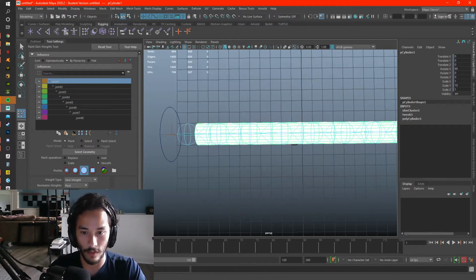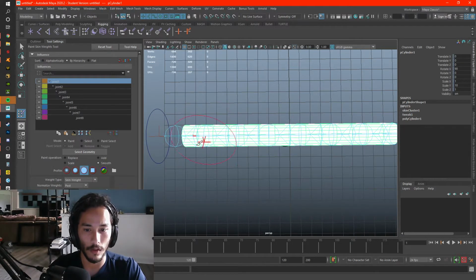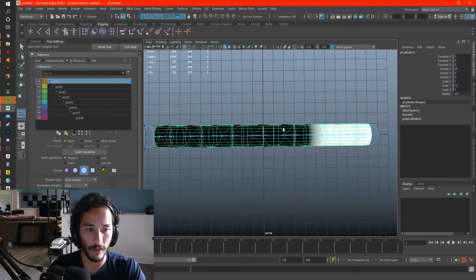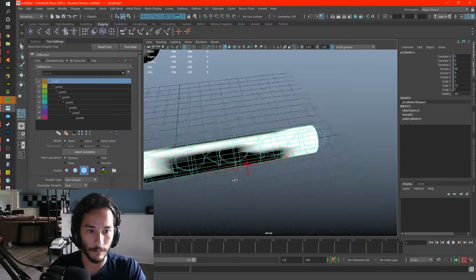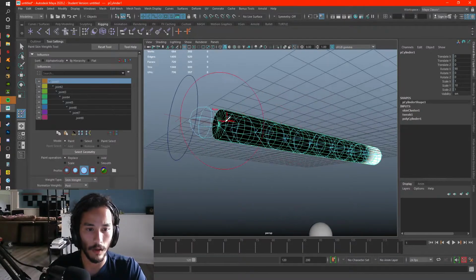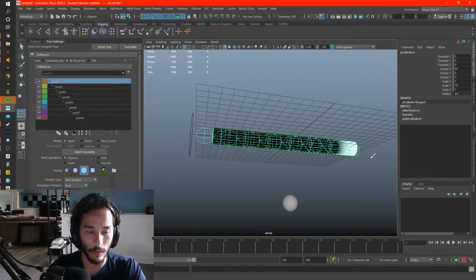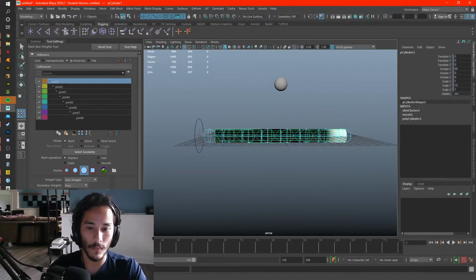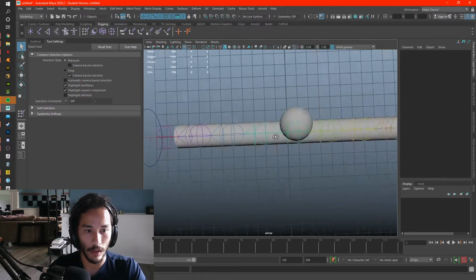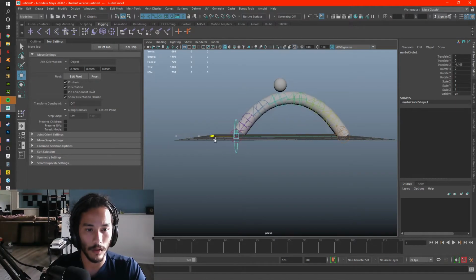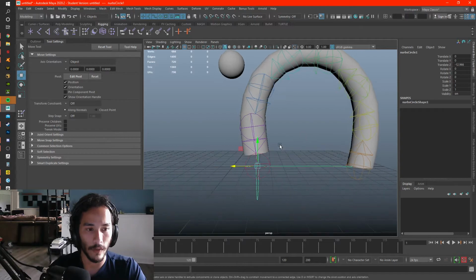This is the first joint in the chain, so I would actually have to remove all these weights. So I'm going to go back to replace. I'm going to hold control and it's going to give me the opposite of my value. I have value set to 1, so holding control gives me 0. I'm just going to paint back up to this joint that I started with. Otherwise, the whole mesh will be partially influenced by the first joint in the chain. And then I'll go back and flood this real quick. This probably won't look all that great, or it might work perfectly fine. Yep. So now the weights are all there.